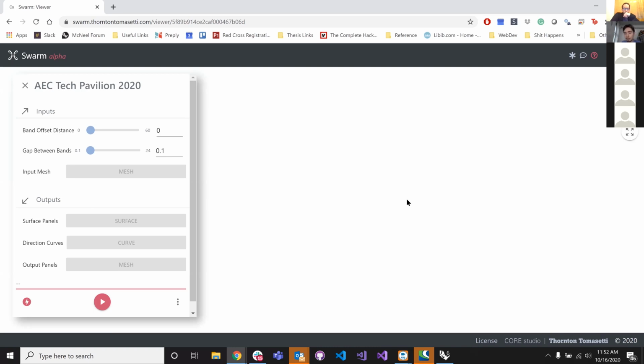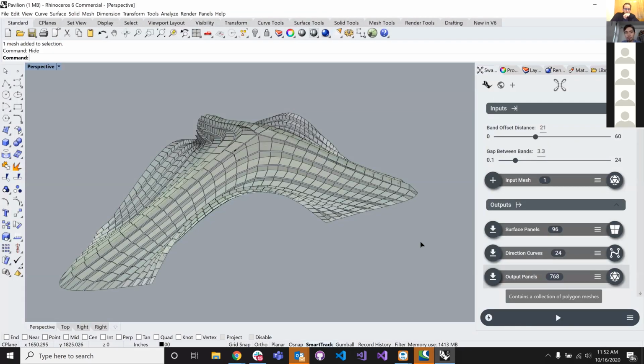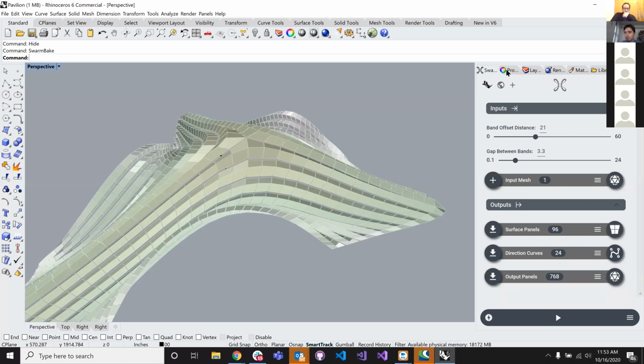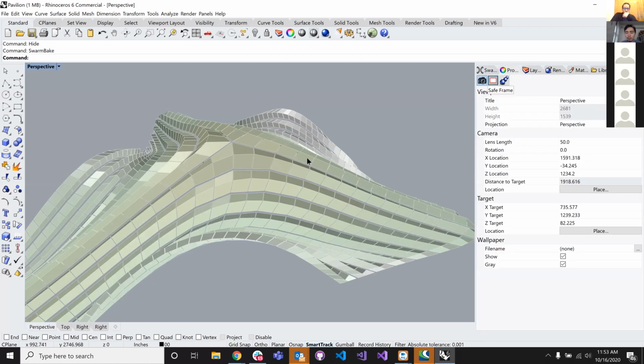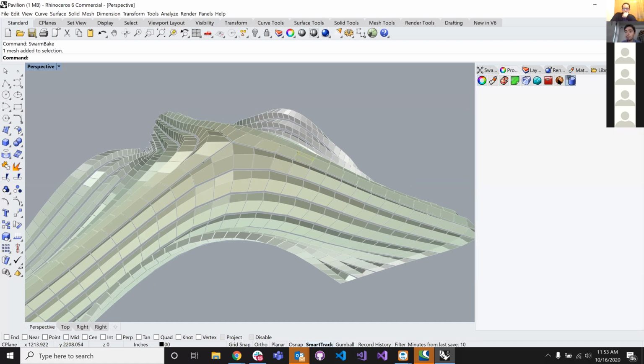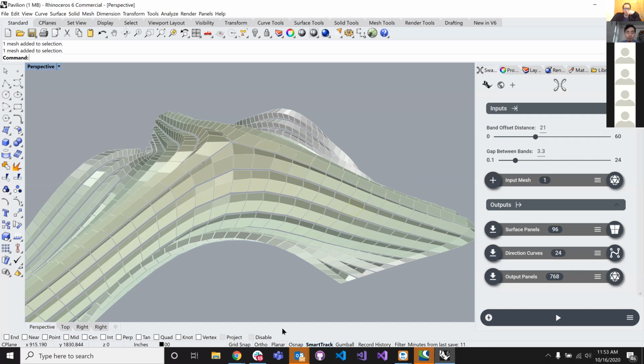And actually, let me show this to you in Rhino. So if I bake those panels, hopefully, and that might have some additional setup needed, but in the properties tab, yeah, so now we have the mesh area here that's been calculated for this panel. And this is something we can use. It's already baked into the geometry. This is something we can use further in our workflow.